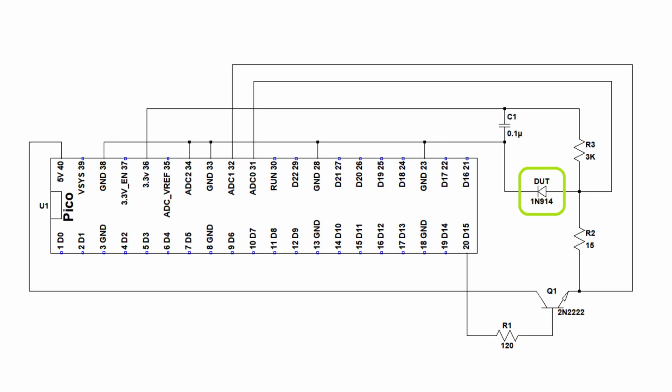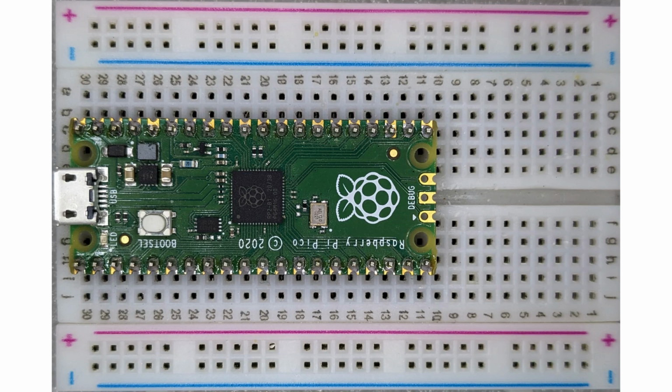The circuit uses +5 volts DC from the Pico. It is important to double-check wiring and component orientation. Miswiring can place 5 volts on one of the I/O pins, and the Pico will be damaged. Insert the Pico into the breadboard.